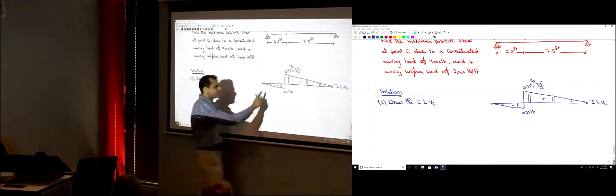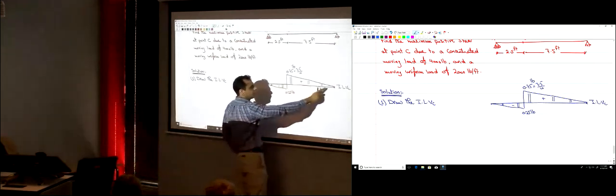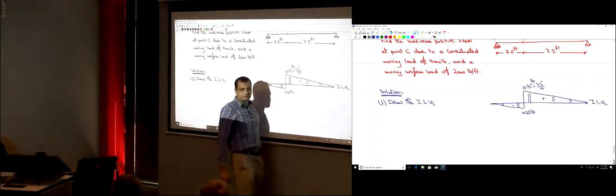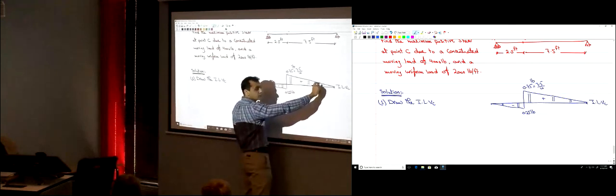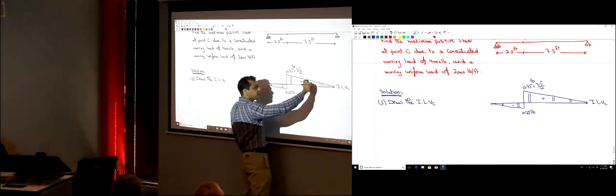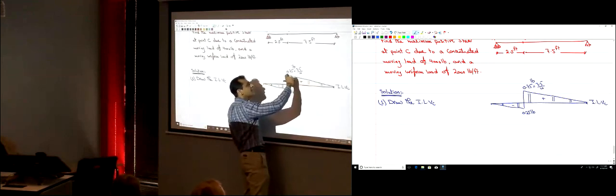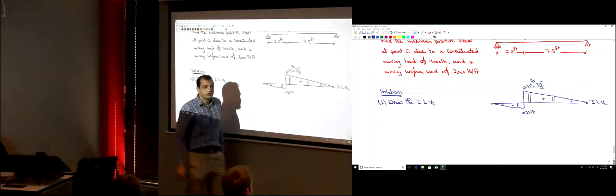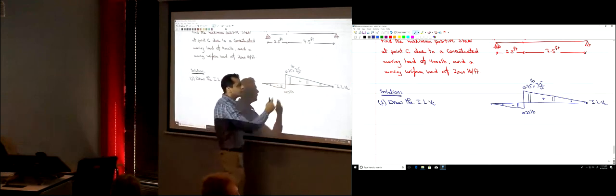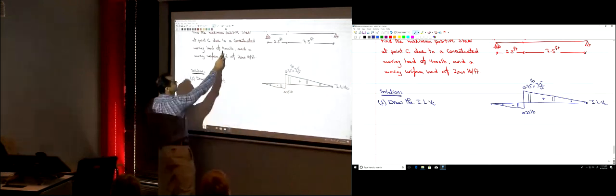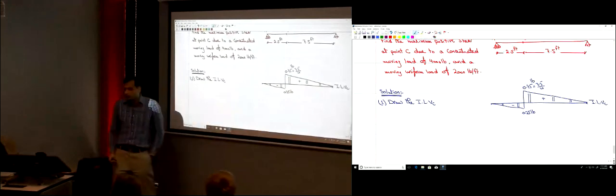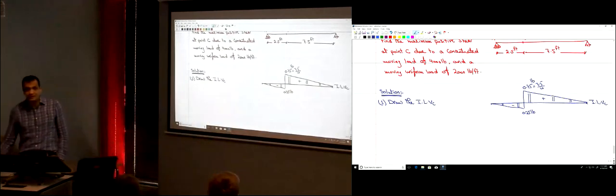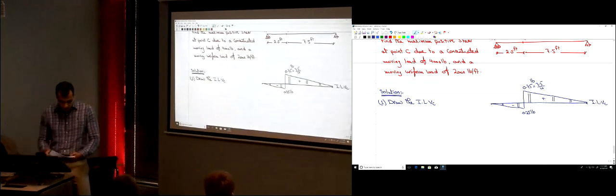So where would you put it? Definitely you want to put it here. If I put it here, it will give a VC of that height. If I put it here, it will give a larger one. So the maximum is over here, just right. So I just put my load over here. But it's not a unit load, it's 4,000 pounds. That's the influence line. The influence line helps you to know where to put your load.